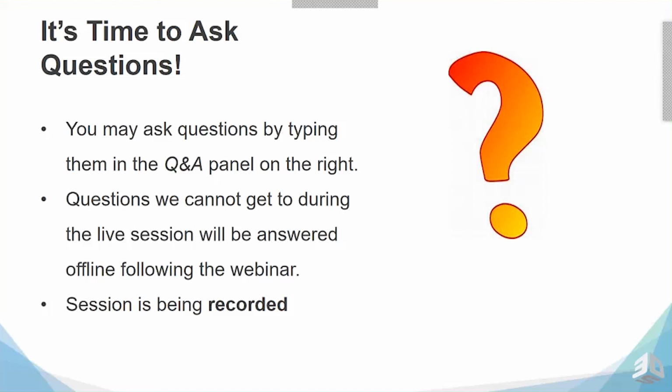The suggestions for orientation aren't necessarily tied to the build simulation at this point, but 3DXpert does have a wealth of tools to help you analyze your orientation. So you can do minimum supported area, Z height, a lot of things like that. But it will definitely take some manual, I guess, intervention to decide what the best orientation might be.